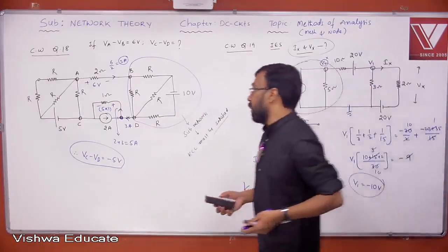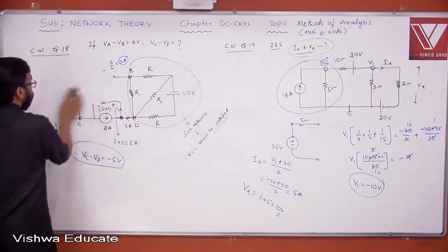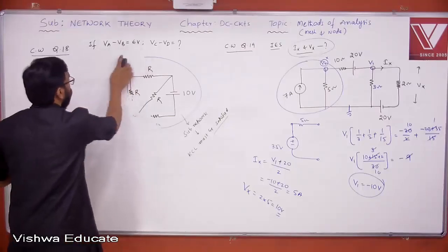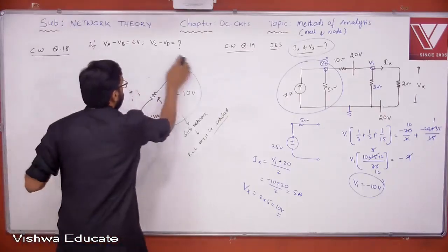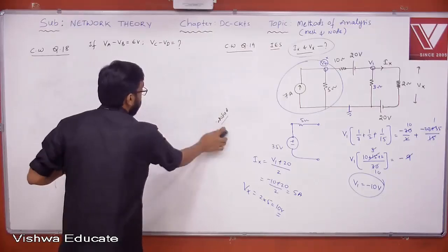Meanwhile, I will note down another problem, so please quickly do that. Always utilize that opportunity when there is a current source. When there is a current source with a parallel resistor, don't miss that opportunity. You can reduce the number of equations using node analysis.